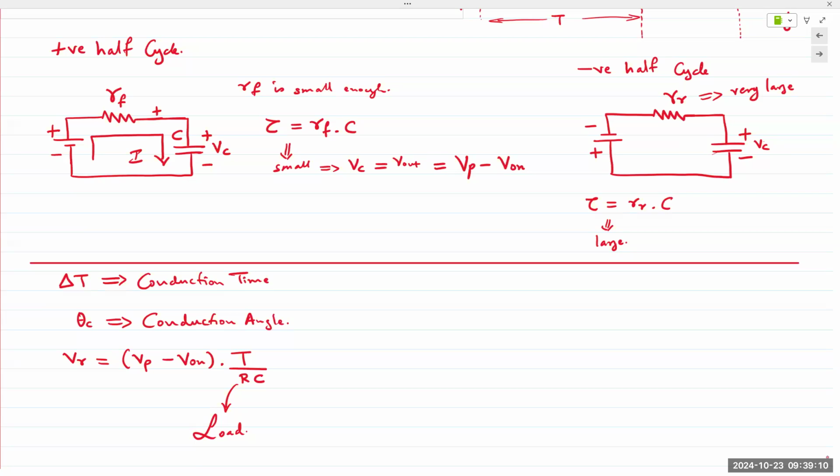So as a design engineer, the value of that R is a consideration in the design process. Whether you are designing it to work with one single device, or whether you're designing it to work with a wide range of devices. In our case, right here, we'll simply say it's a single value, and we will choose it so that the time constant is sufficient enough to give us a near flat DC line.